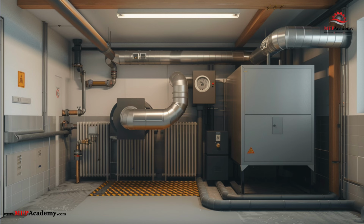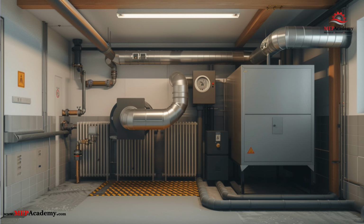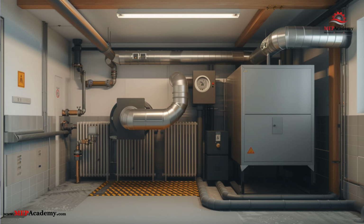This system typically consists of two separate pipes for intake and exhaust. Direct vent systems improve efficiency by not using indoor air for combustion and minimize the risk of indoor air contamination. In addition to enhancing efficiency and safety, direct venting systems offer several other benefits. They reduce the risk of backdrafting, which can lead to the infiltration of harmful combustion gases like carbon monoxide into the living space. Direct venting also allows for more flexible installation options, as these systems can be vented horizontally or vertically, making them suitable for a variety of building layouts.